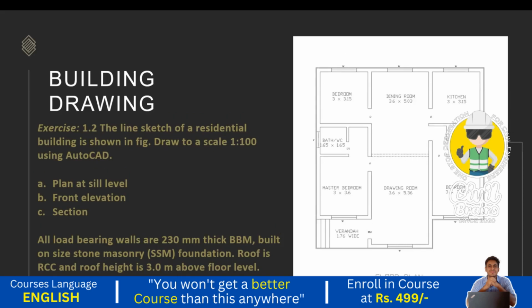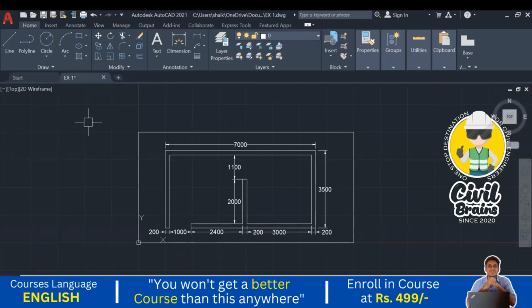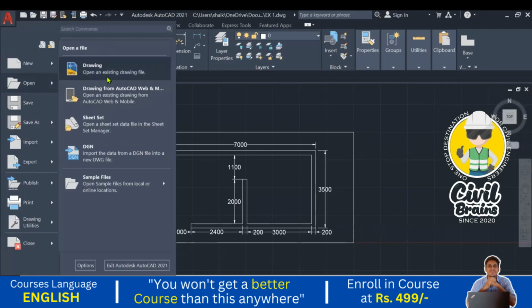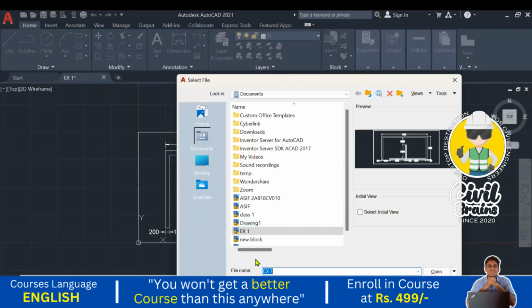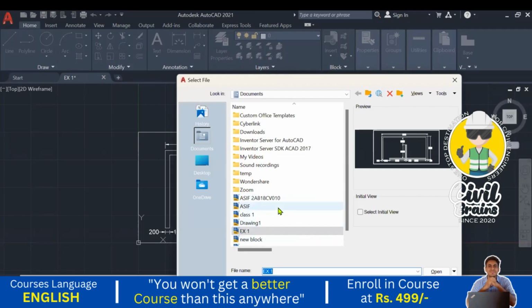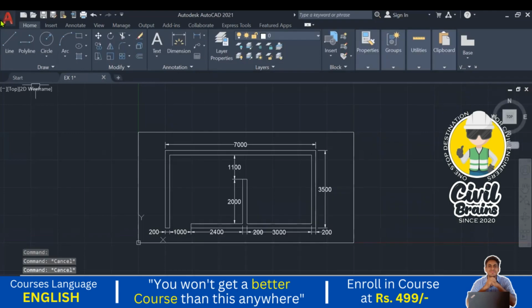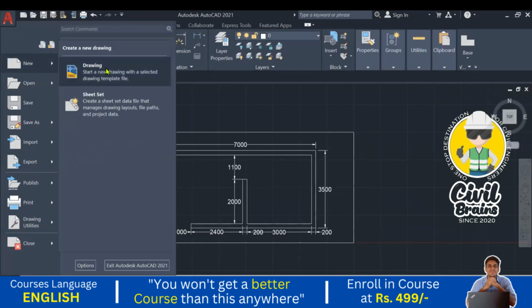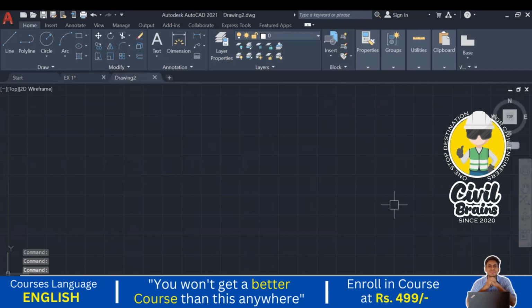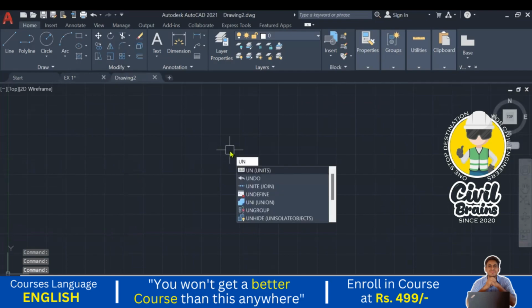Okay, I just take a new page here for exercise 2. I go here, open, new drawing, AutoCAD, open. So you have opened the new drawing. What is the first step of starting any drawing? You need to set the units.